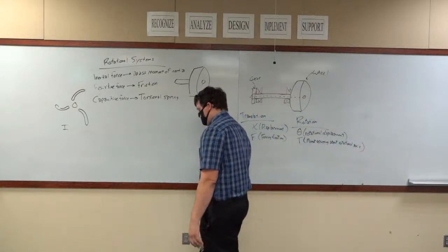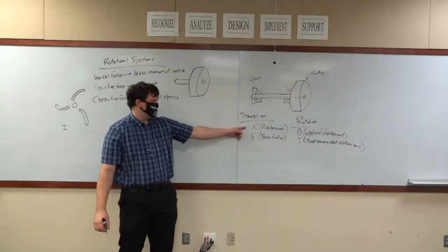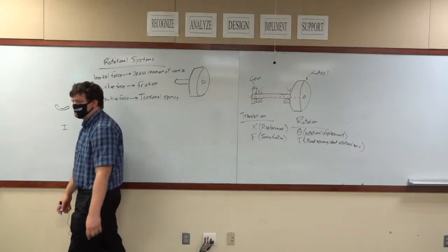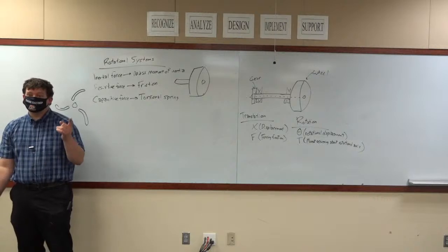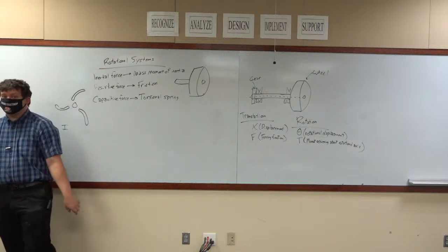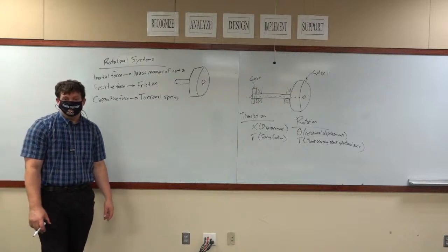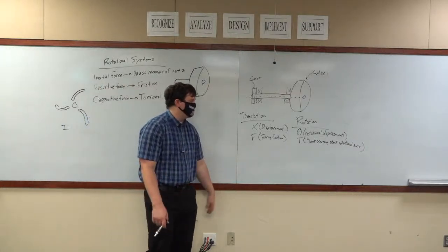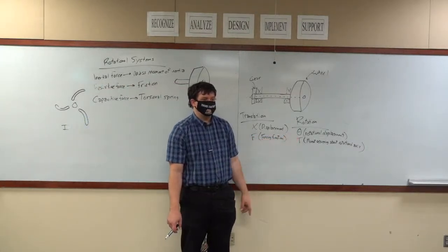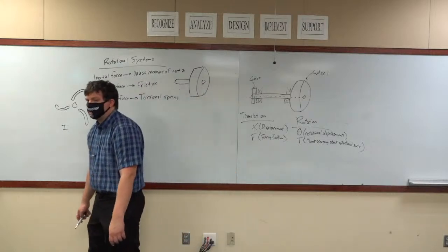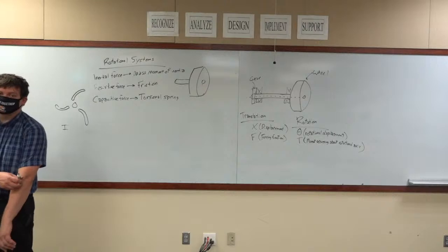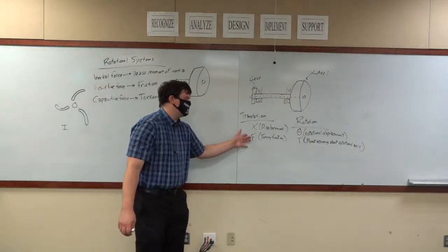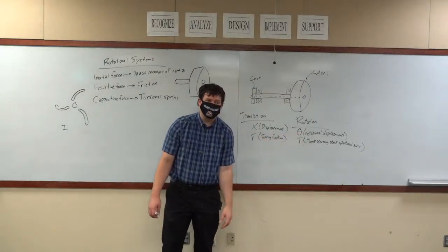Okay? Force times distance. Anybody know what that is? A force times a distance is the energy that is contained in a spring. It is a formula for energy. You have to divide that by 2. The distance multiplied by the torque is the energy contained in a rotational system. We're dealing with identical things. Okay? Take the time derivative of this, it's power. Take the time derivative of these two multiplied by each other, it's power.